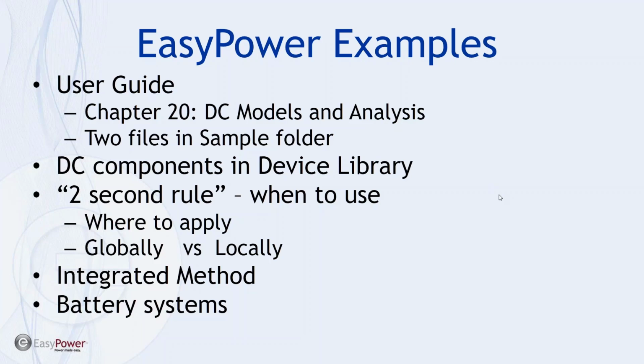And it's an advisory comment in the verbiage of IEEE, and they make the addition that sound engineering judgment should be applied before the 2-second rule is utilized in any circuit. And so that's why I'm reluctant to just automatically set any system up for 2 seconds. I think that covers everything I wanted to touch on.